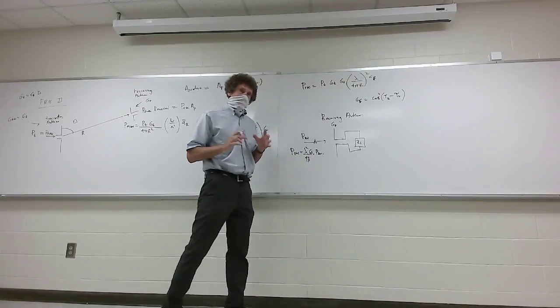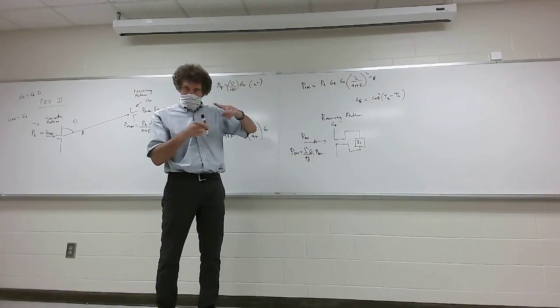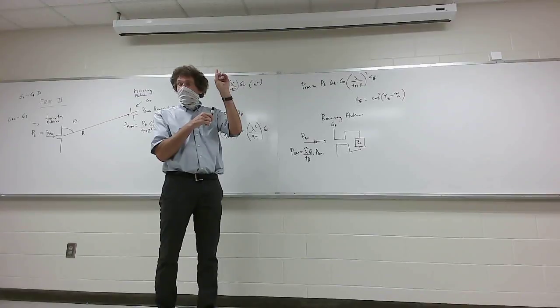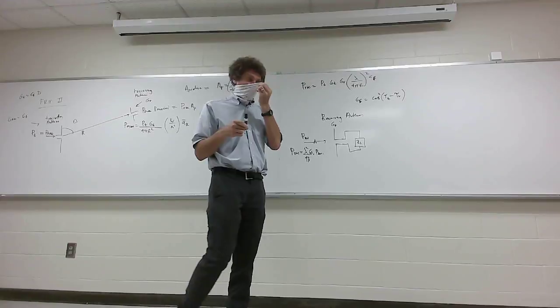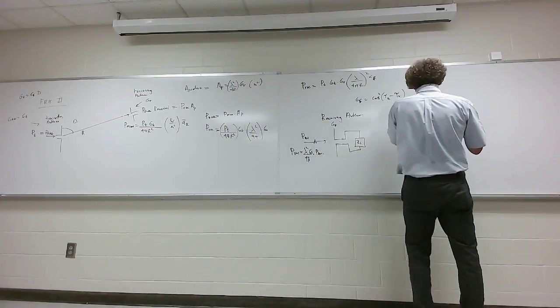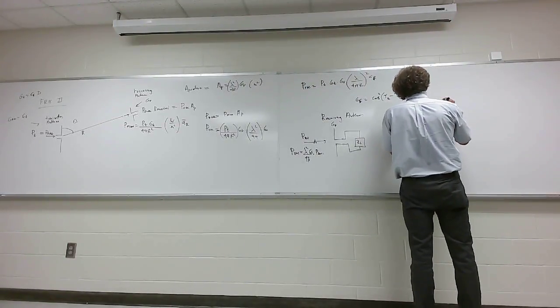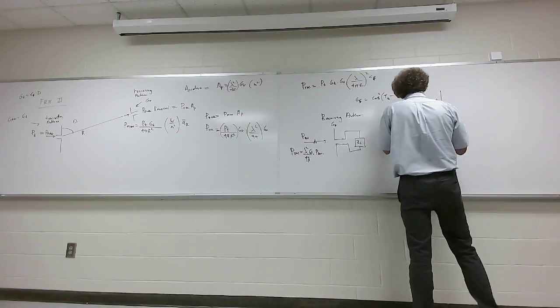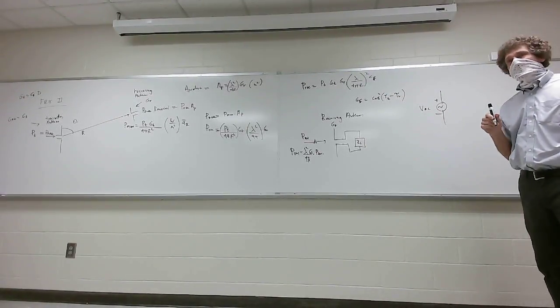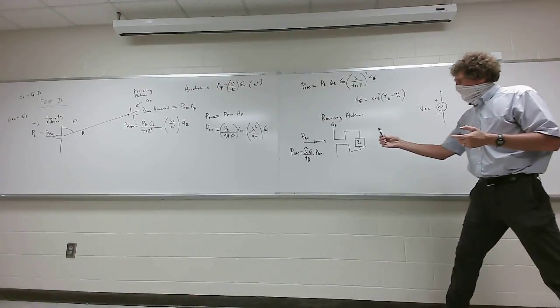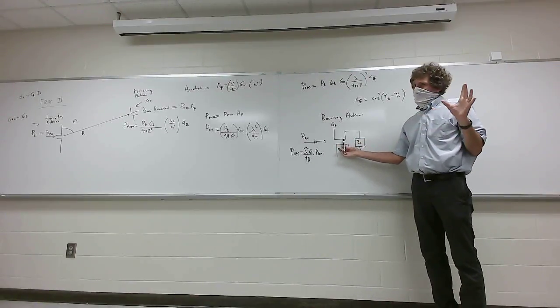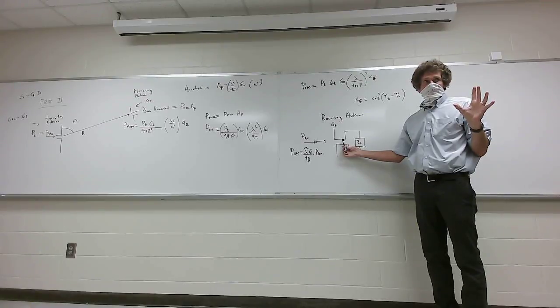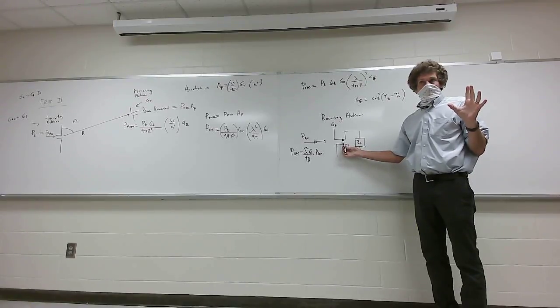Now, here's the thing. I'm trying to show you a schematic where I draw a little cartoon of an antenna with a load. Electrically speaking, as engineers, we probably look at this a different way. We're going to say that the antenna itself will have some equivalent open circuit voltage. This will be an AC voltage. If you think about it, the antenna's got a wave coming in. If there was no load, there has to be an open circuit voltage developed. Do y'all agree with that? No current would flow. It should make sense.